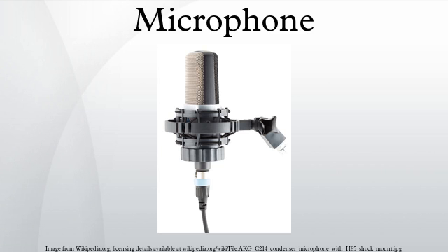Shotgun and parabolic microphones. Shotgun microphones are the most highly directional. Their directional pattern has a very narrow lobe in the forward direction and rejects sound from other directions. They have small lobes of sensitivity to the left, right, and rear but are significantly less sensitive to the side and rear than other directional microphones. This results from placing the element at the back end of a tube with slots cut along the side. Wave cancellation eliminates much of the off-axis sound. Due to the narrowness of their sensitivity area, shotgun microphones are commonly used on television and film sets, in stadiums, and for field recording of wildlife.